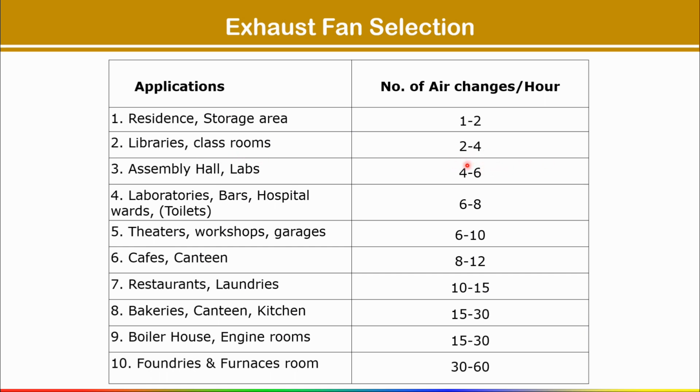In 1 hour you have to change the air 4 times. ACPH value you have to take 2 to 4. Assembly hall, labs 4 to 6. Again laboratories, bar, hospital ward, toilet, so in that you have to maintain 6 to 8 ACPH value.